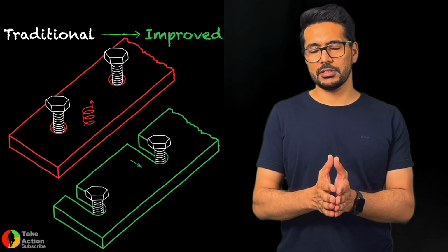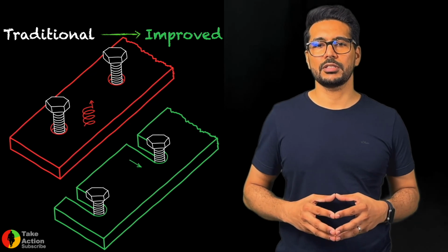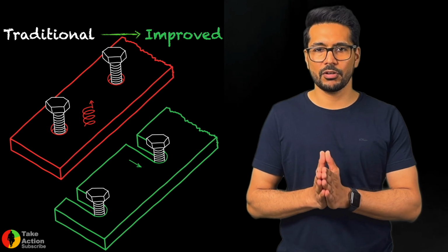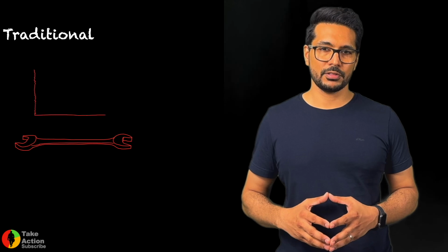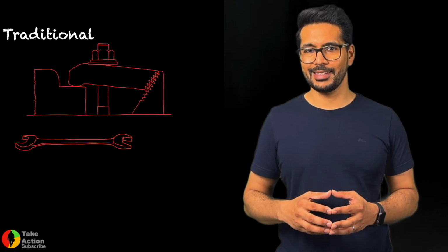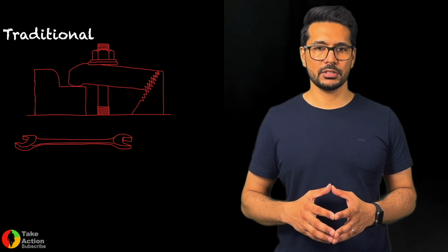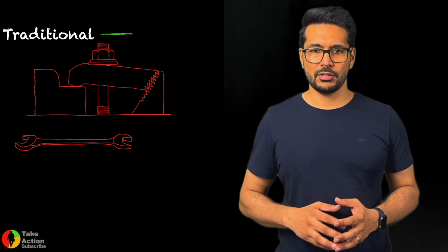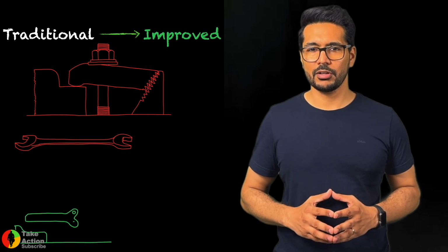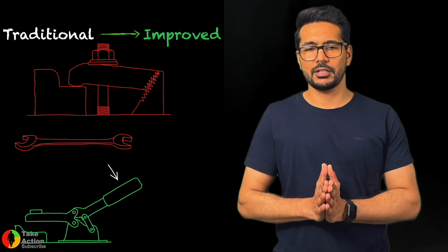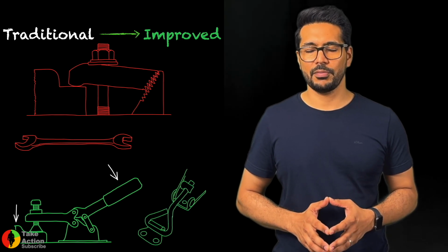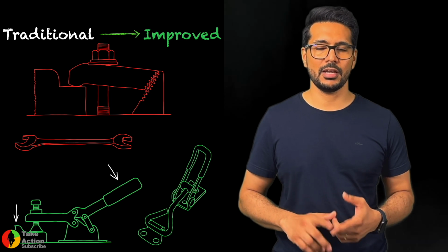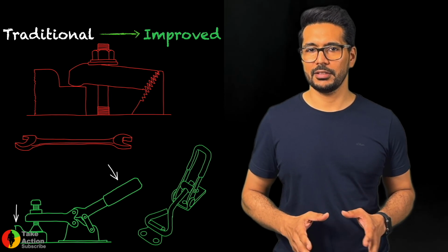So these are the ways in which you can speed up the whole replacement of the parts during the setup time. So in case the setup time involves any fastening or any clamps with bolts which requires spanner or other tools, that you can also check. There are in the market a variety of clamps which don't need any type of spanner, Allen key or anything like that.